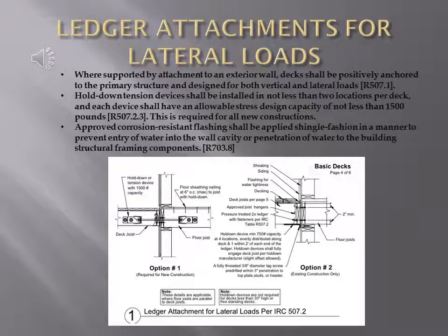Approved corrosion-resistant flashing shall be applied shingle fashion in a manner to prevent entry of water into the wall cavity or penetration of water into the building structural framing components, IRC R703.8.